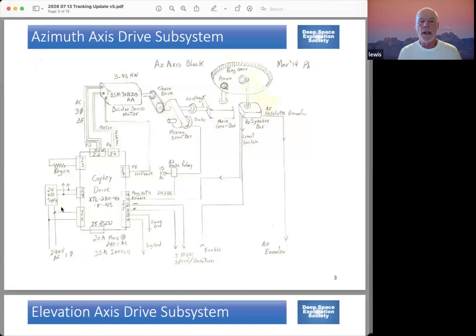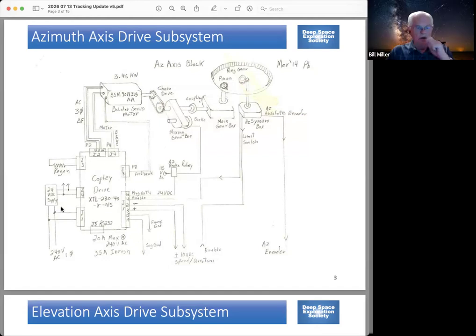I think, just as an aside, it would be good to have a switch in the tower and in the ops building that can turn that off. Now, Lewis, there is a second breaker that controls the 240 volts into the system, in the tower at the third level next to all this equipment.